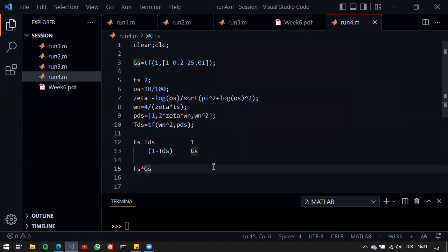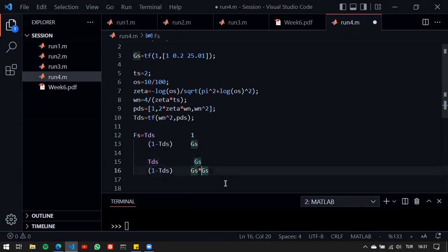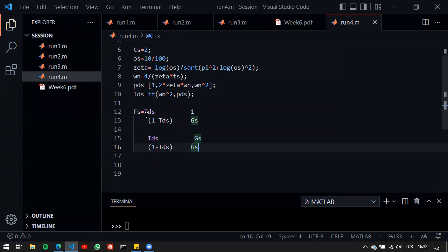So at this point, if we plug in this here, we'll get a pole zero cancellation, basically, or we cancel out all the poles of the system and all the zeros of the system with the controller poles and zeros. So if the pole zero cancellation is not exact, then we are basically in trouble for this controller because it is based on this cancellation.